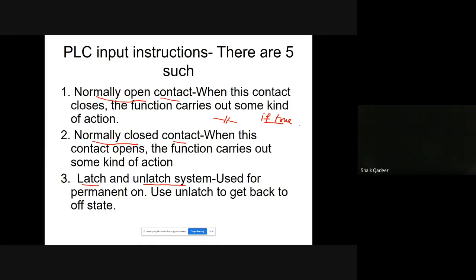And the second one, normally close. Its symbol is like this. The meaning of this is if false. Maybe I'm writing the C equivalent code: if true, inside the braces, whatever we want we write. So in this case, the output gets the high logic if true, and for normally close, the output gets the high logic if false. In this particular case, by force,